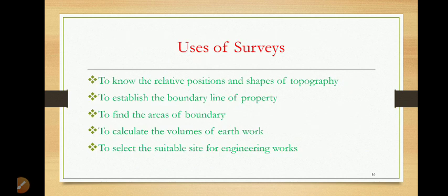Let's see the uses of surveying. To know the relative position and shape of the topography. To establish the boundary line of the property. To find the area within the boundary. To calculate the volume of earthwork. To select a suitable site for engineering work.